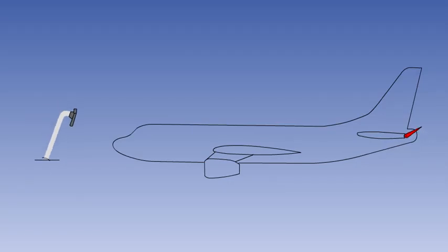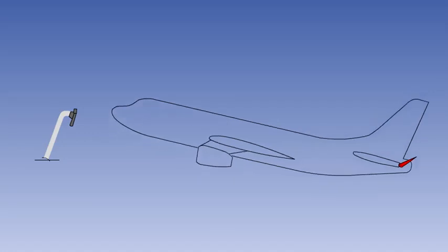If the pilot pulls the yoke or control column towards himself, then the elevator moves up. The degree of movement of the cockpit control directly affects the angular displacement of the control surface. This movement produces an aerodynamic downforce on the tail, which will pitch the aircraft nose up.